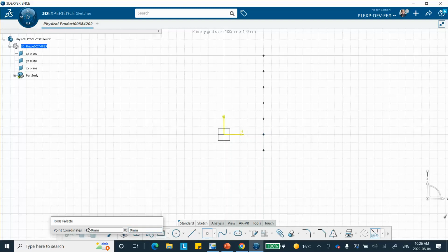Now the other ones are on the outside of the bellow, so the coordinate is 100, and the first one has a y coordinate of 10, enter, and then 100, tab 30, enter, 100, tab 50, enter, and 100, tab 70, enter.